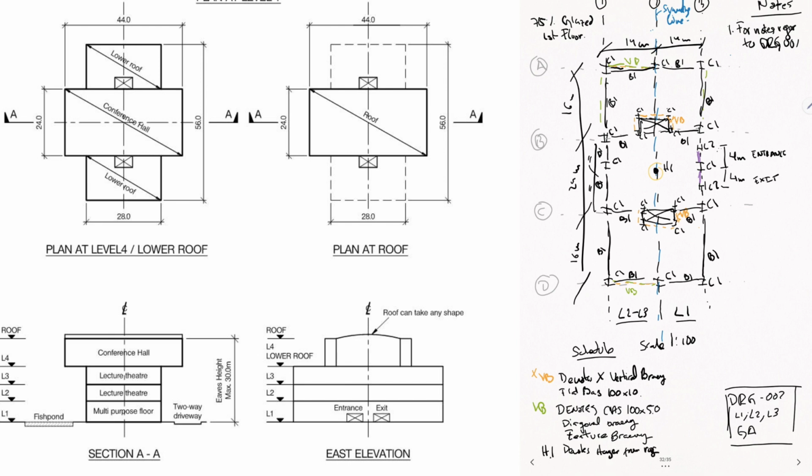I also included the location of the vertical bracing and made sure that it's stable in all directions. I also included the location where the openings were, just to make sure that it was identified that there was an opening in there and that there was no column or bracing blocking the entrances.